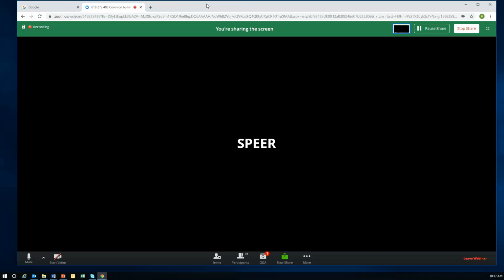Right, yeah. Okay, and then my first ever question about climate zone 6A and 6B, and this is the last one. For an exterior wall residential application in climate zone between 6A and 7B, do I need vapor barrier control? If it does, what side of the wall does it need to be on? Well, if you're in a cold climate zone, it wants to be on the warm side of the wall in the wintertime, which is most of the time in 6 and 7, more than it is hot. So the vapor retarder wants to be on the warm side of the wall.